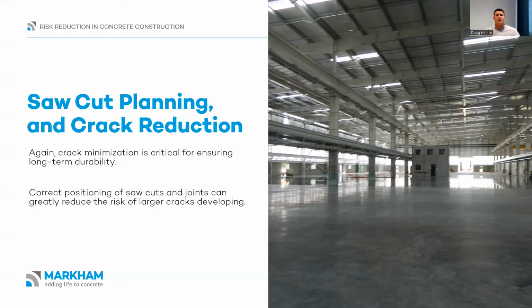And what happens if you don't do proper planning around this area is you end up with a random cracking pattern, like a map cracking pattern, and it's much harder to remediate. It doesn't look good visually, and it's much better to have a planned nice straight line in a saw cut or a construction joint that you can seal properly. It's much easier to seal something that's in a straight line versus a crack that follows a random pattern across the slab.